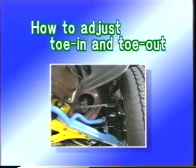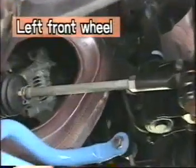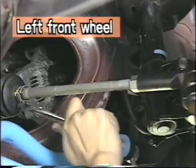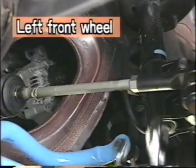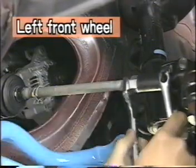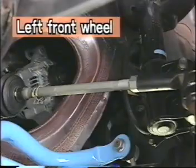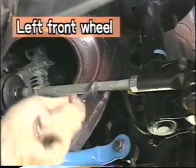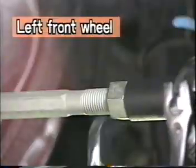If toe in or toe out are not within specification, adjust them. To make an adjustment, remove the boot clips and loosen the tie rod lock nut. Turn the left and right tie rod ends an equal amount to adjust the toe in and toe out in accordance with the specification given in the repair manual.